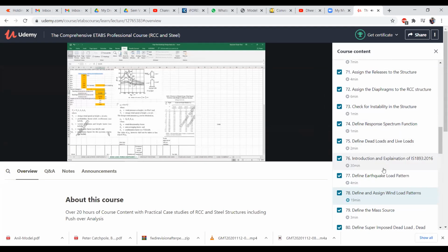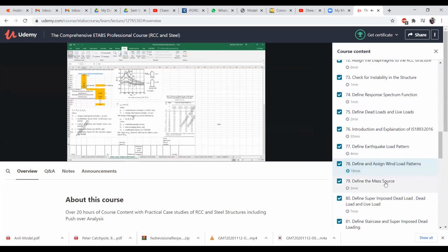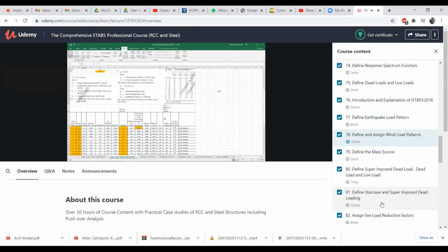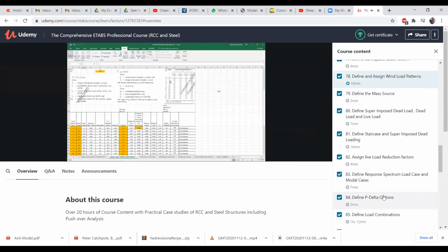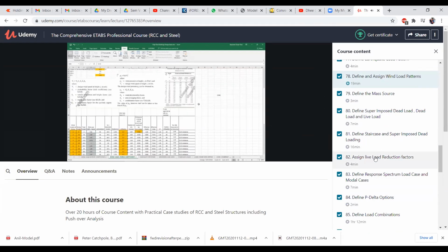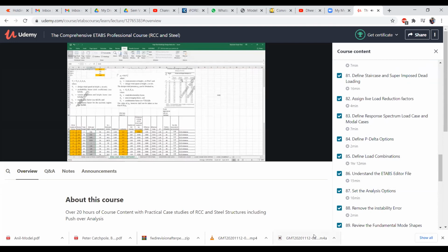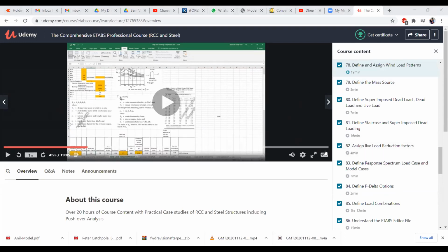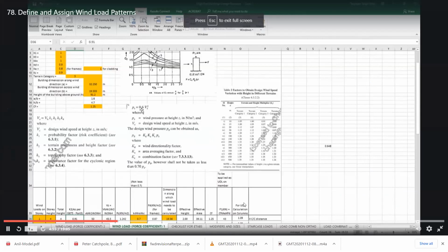As Delhi is in a non-cyclonic zone, we can go ahead with 1. Kd, Ka and Kc are other factors that we will study later. But now K1 is clear, K3 is clear and K4 is clear. K2 we need to enter manually as per the different heights. That is, if the height varies, K2 varies. So we need to enter all the K2 data here as per Table 2. We can calculate Vz, and after calculating Vz, we can calculate Pz, that is 0.6 into Vz square.